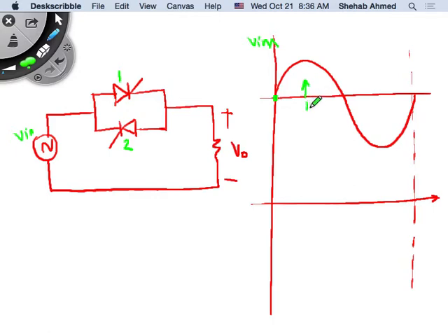This is to device 1. And then in the positive half cycle, I don't provide anything to thyristor 2. It's looking in the opposite direction anyway. As a diode, it wouldn't have conducted. So then in the negative half cycle, I provide the gating signal to thyristor 2 somewhere here, right? So now what will my output voltage look like?